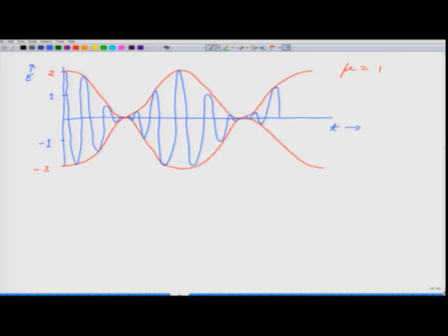And the envelope of the amplitude modulated wave now represents the original modulating wave very nicely. There is no information that is lost if mu is equal to 1. So, the maximum value of the amplitude modulation index can be equal to 1 for an efficient amplitude modulated transfer.